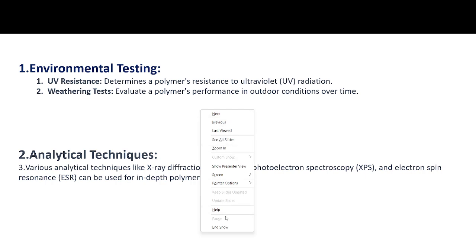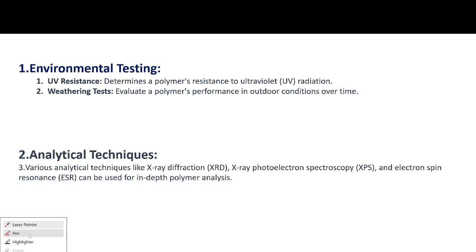But if there is some unsaturation present, any double bond in our polymer system, like a rubber applied in tire applications, then when you irradiate it with UV, the bond can break and become a radical. If it makes a radical, our polymer degradation will start.